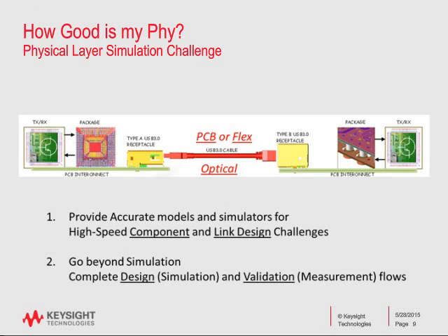So if you're going to be doing simulation, what are you really looking for here? You're looking to measure how good is the PHY, against a specification of some kind. So you clearly need to provide an accurate set of models and simulators that can work with those models. But beyond that, you also need to be able to deal with the complete design, not just the individual parts, but look at the PHY as a whole, and then be able to validate your simulation against measured data. So those are some general challenges of working in the PHY arena. In the case of electro-optical, we need to be able to deal with both the electrical and the optical in one simulation if we can.